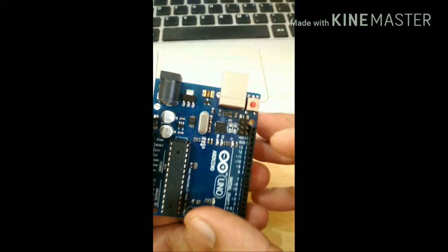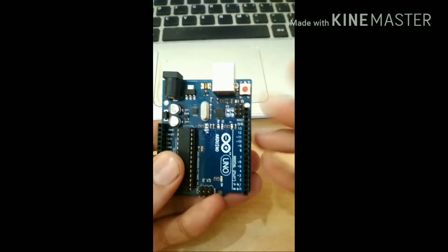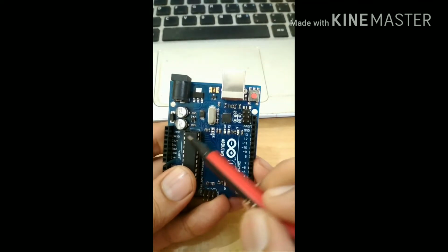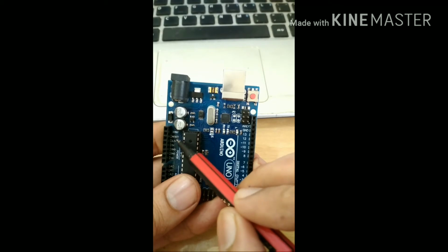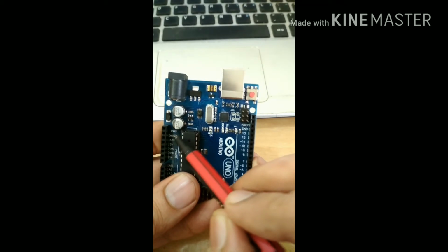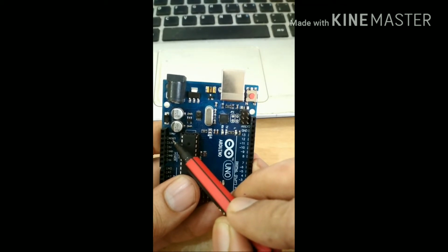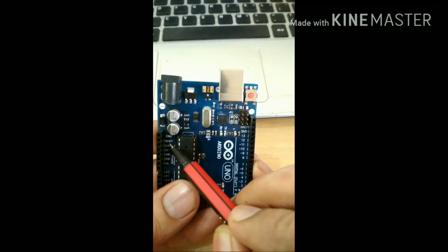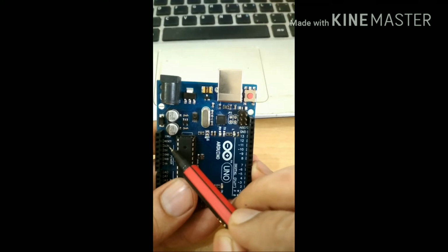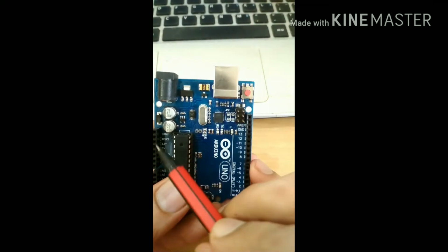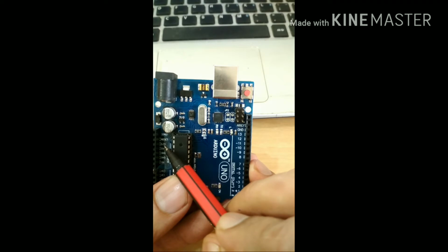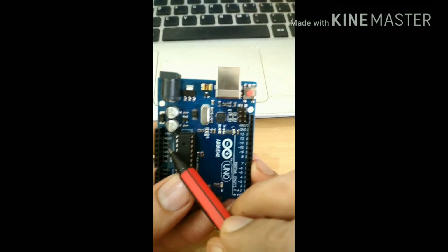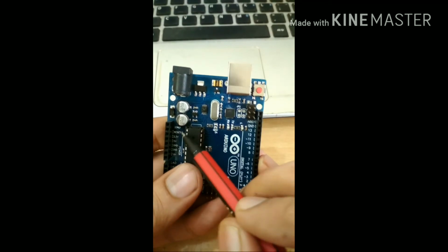Then Arduino reset. There are two Arduino reset buttons. One is on the corner of the board and the second one is on the power pins side, that is reset. You can reset your Arduino board, or you can start your program from the beginning. You can reset the UNO board in two ways. First, by using the reset button on the board, and second, you can connect an external reset button to the pin labeled reset on the power pin panel.